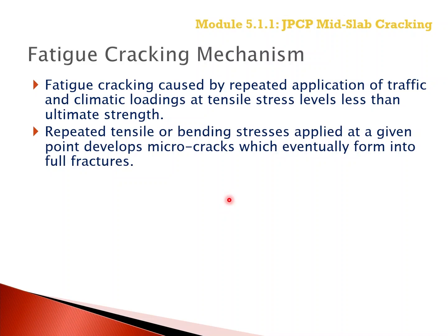The repeated tensile or bending stresses applied at a given point develop microcracks that eventually form into full fractures at critical points along the slab.